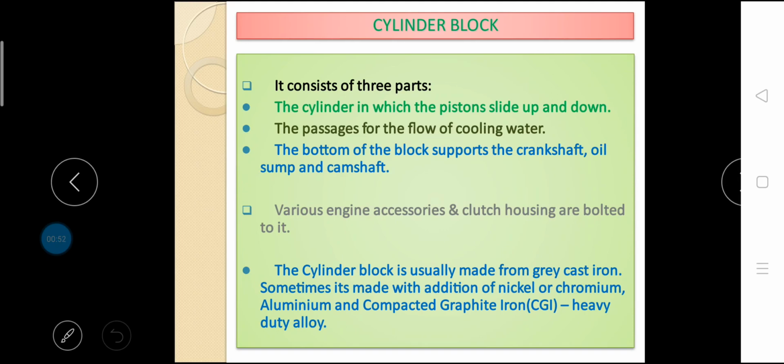In case of a closed deck, circulation of the coolant is provided by vertical drilled holes meeting with the corresponding holes in the cylinder head. This is preferred over the open deck on account of its greater reliability to provide a leak-proof joint, although the latter is relatively easier to produce.